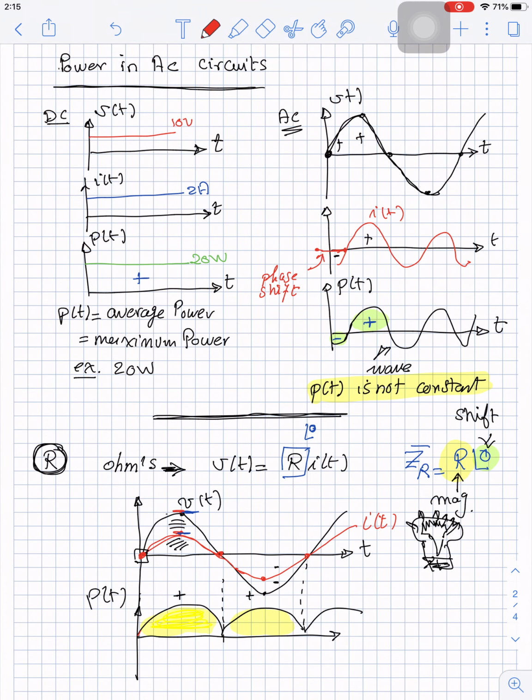You will see that the power is increasing. It reaches a peak, then it goes down to zero, then it increases again, goes to peak, but it's always positive. If you think about a heater, it's not an issue. If you take power, then the power is variable. At the end, you will see the average temperature. The thermal time constant is so high, you will not see any oscillation in the thermal power or in the thermal application. So this is totally fine for heaters.